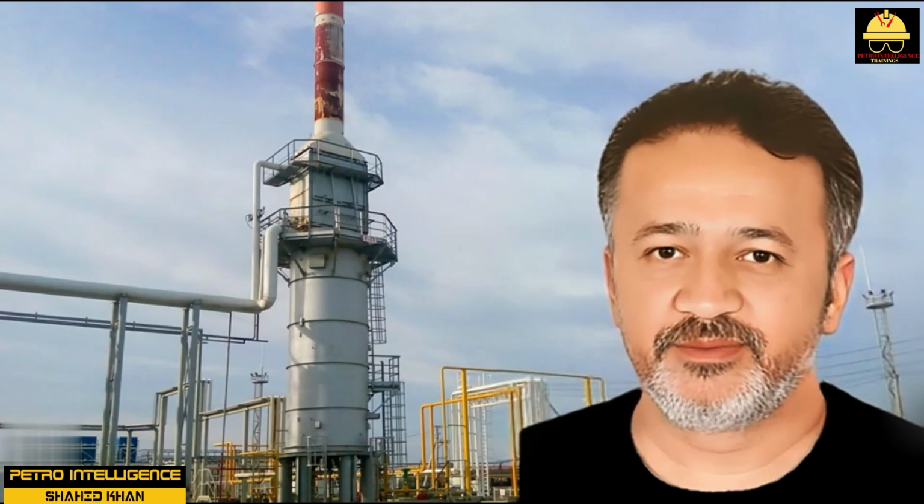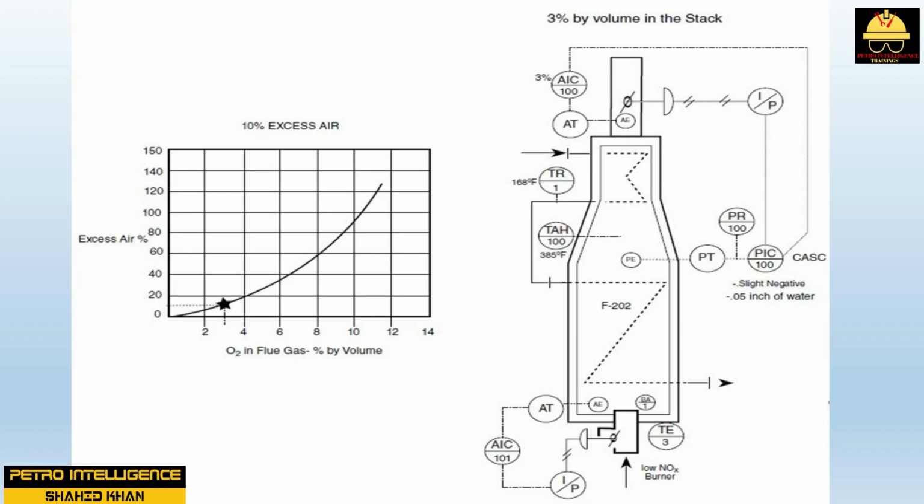Air-to-fuel ratio. Unit specifications require the console technician to decrease the excess air so that temperatures in the process heater will increase. As the excess air is decreased, the heat transfer rate near the burners is increased. Because the net heat released from the natural gas burner has not changed, the amount of heat contained in the hot combustion gases slows down and has time to soak into the exposed tubes. This process reduces the amount of heat transferred in the convection section and lowers the temperature in both the upper convection section and stack. This process provides a more efficient way to prevent heat energy from flowing out the stack.